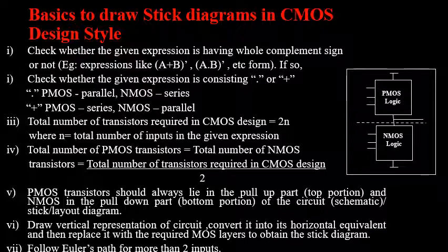Make sure that you remember all these 7 rules before drawing any type of diagram, either a stick diagram, layout diagram or circuit diagram. Must and should, you have to go through these 7 rules. First and foremost, you have to look into the expression which they have given. In general, they may ask you to draw the stick diagram of an inverter, 2 input NAND gate, 2 input NOR gate, XOR gate, like that, wherein you are supposed to write the equation which you already know from your digital electronics subject.